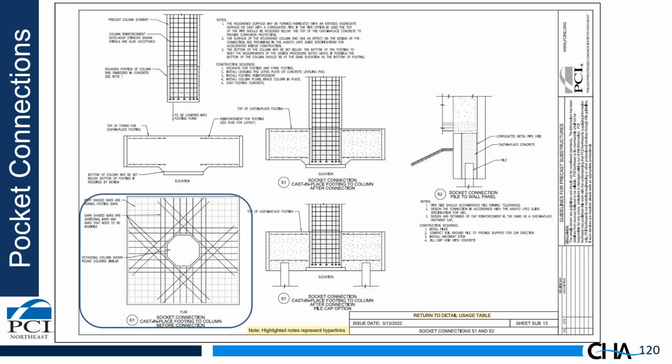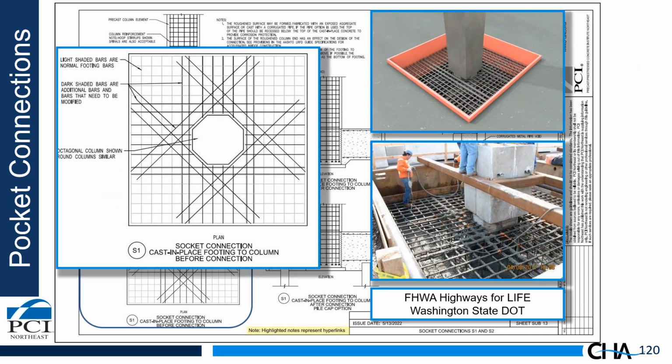So take a look at the footing. We essentially can set the column in the footing. We have to cut several bars and relocate them. The darker bars are the bars that have been added to the conventionally reinforced footing, both horizontal, vertical, east-west, north-south, and diagonal bars in the corners to control cracking.